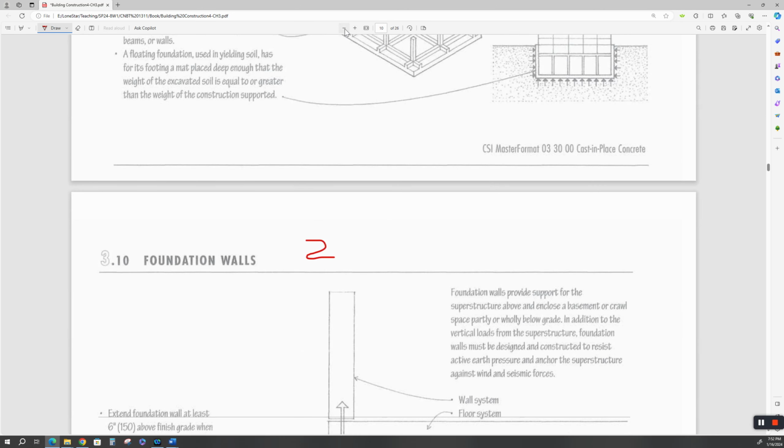These joints are very problematic. This detail can cause you a great deal of grief if you're not careful how to handle it. I'm not saying this is a bad detail. I'm just saying that this is a potential for water migration. Just because you put some sealant in that joint doesn't mean that it's going to seal. Water is really a nasty devil.